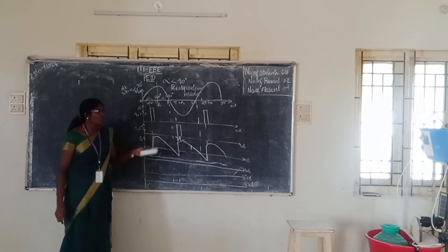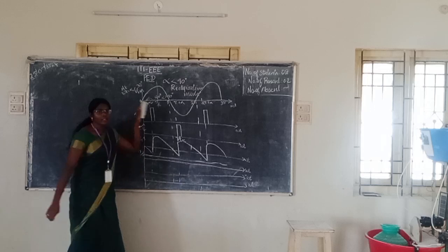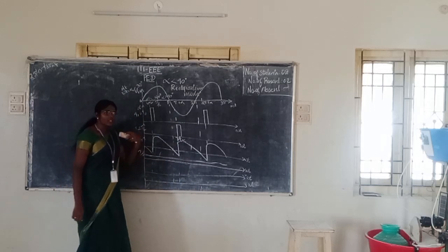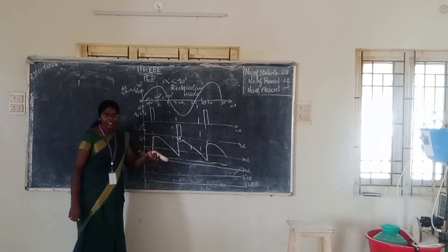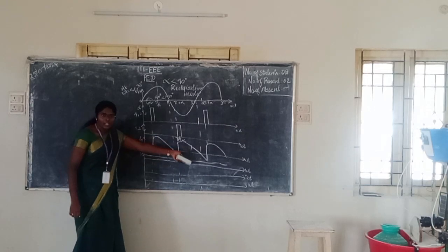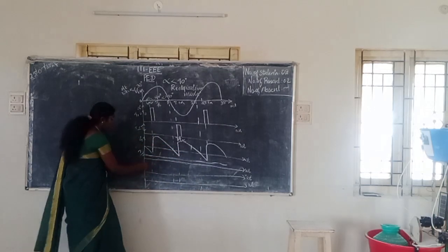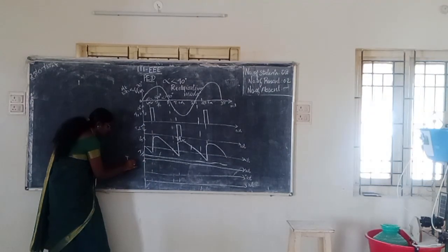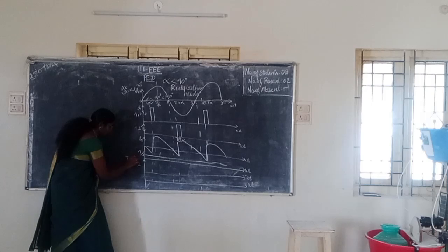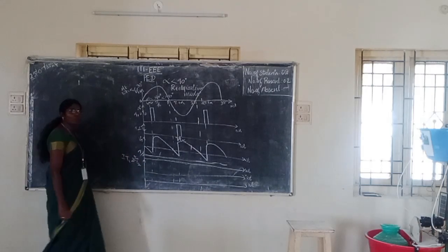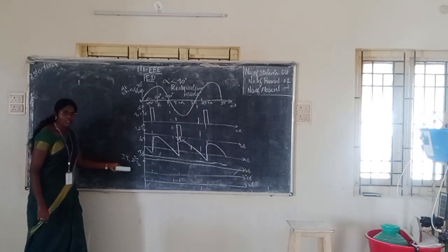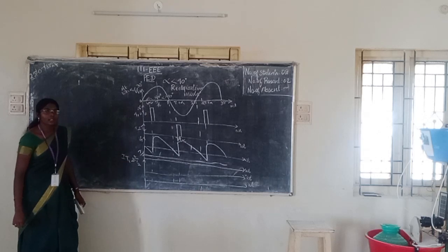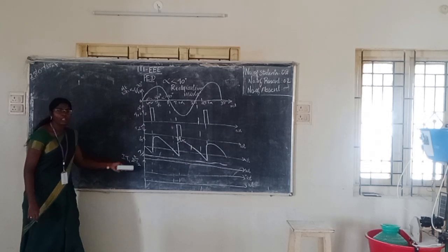So generally the waveform we have seen, where alpha is less than 90 degree, is the rectification mode. Next, what if alpha is greater than 90 degree? What will the inductor do? The stored current will be released from it, so it is in the continuous conduction state. One thing we have to know is what about thyristors T1 and T2, and the current flowing through them.